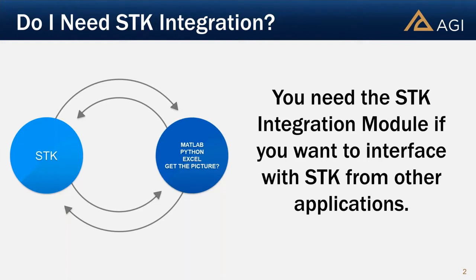So you can integrate STK with MATLAB, Python, Excel, any other tool that you want. We specifically have these as written out tutorials. They basically go over the same scenarios, but you can leverage other tools like C#, Java, and so on. STK gives you your physics-based environment to model your vehicle dynamics, sensors, and different visualizations and physical environments. But these other tools, like Python, Java, Excel, and so on, allow you to do additional numerical analysis, additional plotting for your data, and give you a programming environment to use.